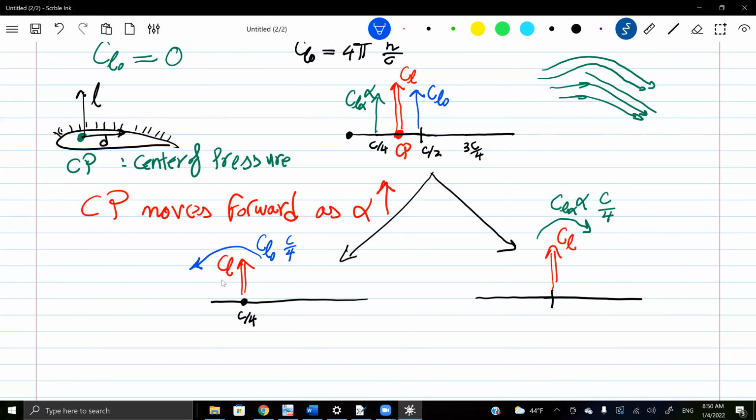So in either case, I will get the resultant lift force for sure. In one case, I will get a moment that varies linearly with the angle of attack. In the other scenario, I get a constant moment that is independent of the angle of attack. So obviously, this is a better candidate. The point itself is fixed, it is always the quarter chord. The moment I get, because I transfer the loads to this point, is constant, independent of the angle of attack. So it seems a reasonable choice.